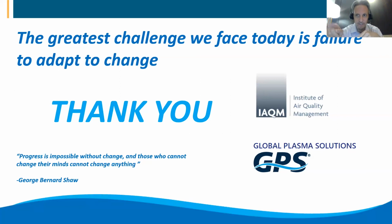After I turn the device on and allow the ionization to come into the space, fill the space, flush, and work for a while to remove particles, and then let the ion concentration settle out, I want to try to read somewhere between 2,000 to 5,000 ions per cubic centimeter, both positive and negative. I hope that answers it. Yeah, that's perfect. Thank you.